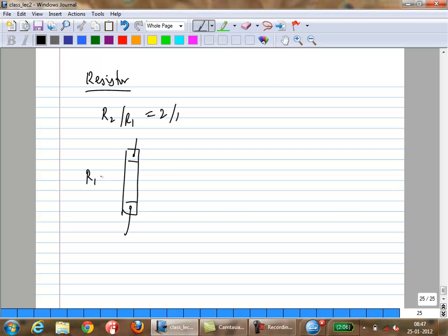And if you want to try to lay out R2 as twice, then that will also have the same. Any value of resistor you add will always have 2 R contact. Intrinsic resistance will change. So there will always be some systematic mismatch component. So how do you get rid of that? Again, same thing, unit cells. Okay? Oops, sorry. This is R2. Okay?